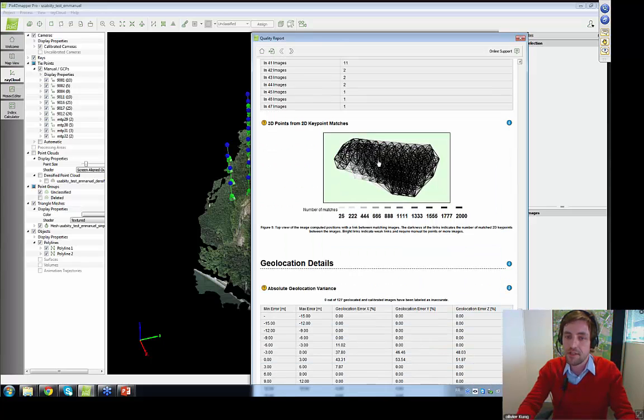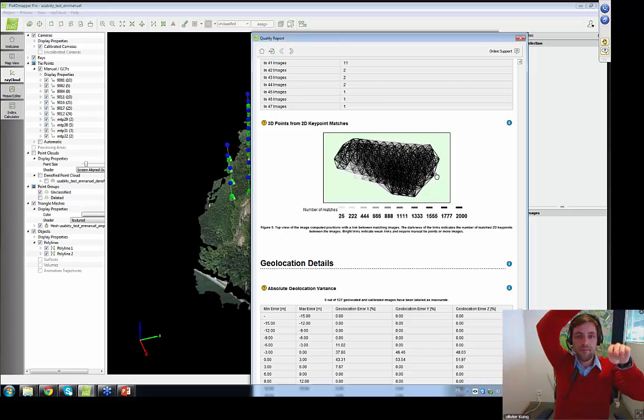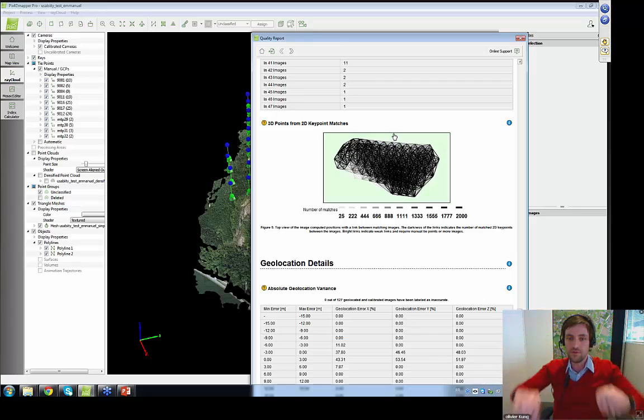Another type of scenario where this type of two blocks may happen is, for example, if you had a mountain in between. So you would have a terrain and a mountain in the middle of your project. Imagine that you keep the same altitude and overlap for each of the images. On the low parts, the overlap will be very good. But if the mountain goes up close to the drone and then goes down, then at the place where the drone is near the top of the mountain, the software will not be able to make any connections or matches, and then you will have a big seam in this graph. There you need to be careful because you know that there are some mismatches between the two.